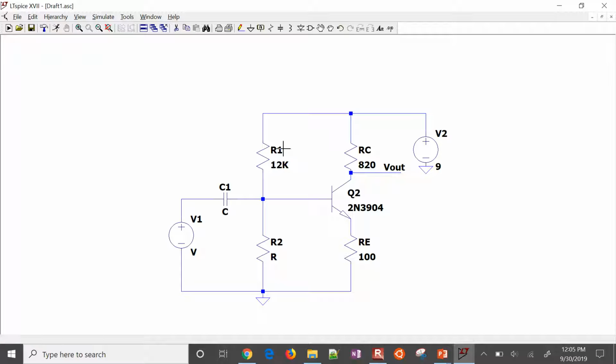You don't want to go too hot. I wouldn't want to do like 1 meg because then my voltage divider wouldn't start working as well. And I don't want to go too low here. And Lab 5 will be operating off a battery, and I don't want to draw too much power. So if I have 12K here, I need to figure out what resistor I want here to get the proper voltage. So what I'm trying to do is I want to have a voltage drop here that might be 0.5 or 0.6. Then there will be a voltage drop across this resistor.